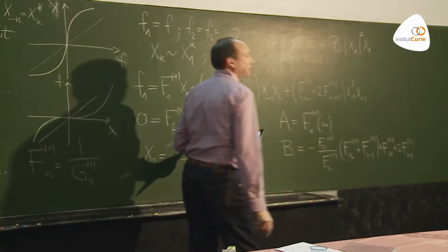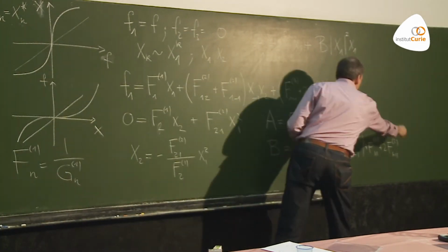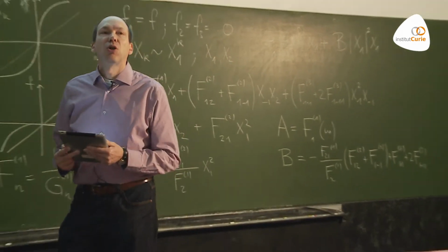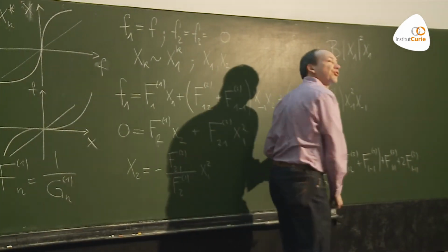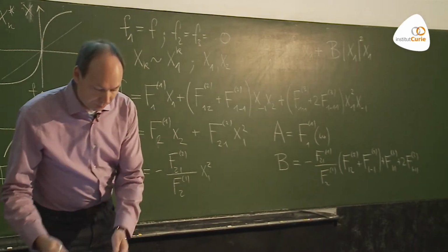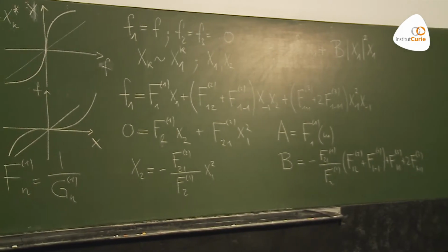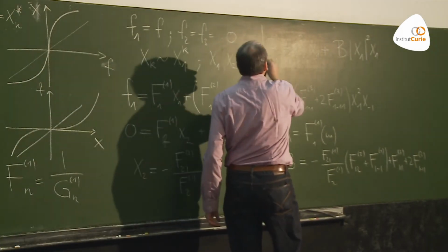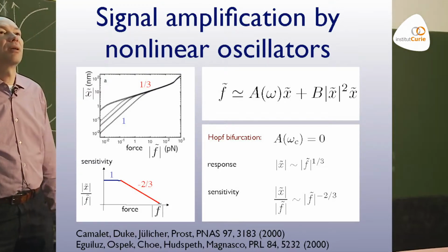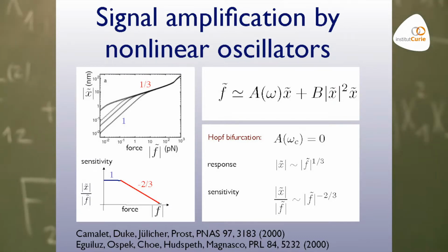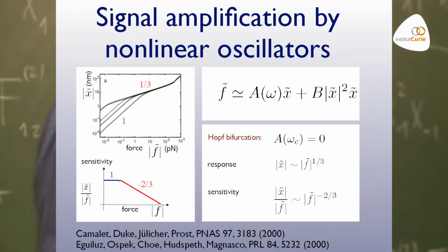So while a is very simple, this coefficient in front of the nonlinear term is a quite complicated combination of quadratic and cubic nonlinearities in the system, and also linear response coefficients. But interestingly enough, even though the system in general has quadratic terms, our generic response between the force amplitude and the response amplitude has no quadratic nonlinearity. The cubic nonlinearity is the first one.